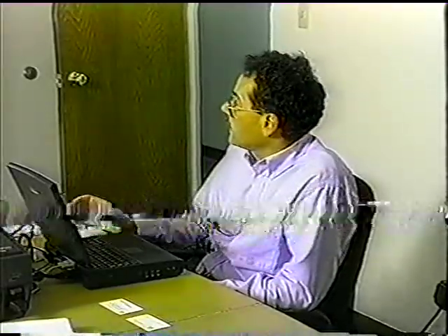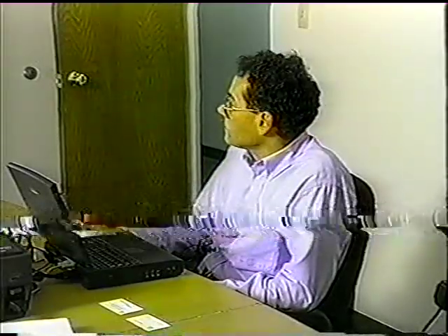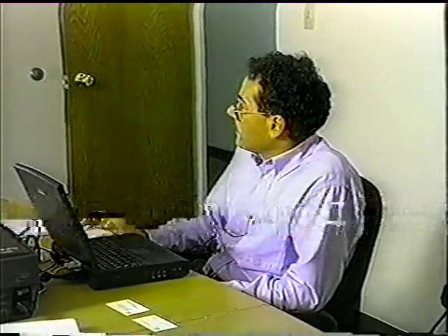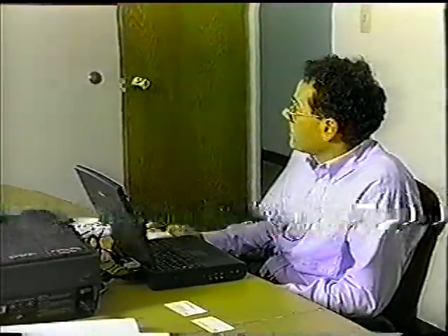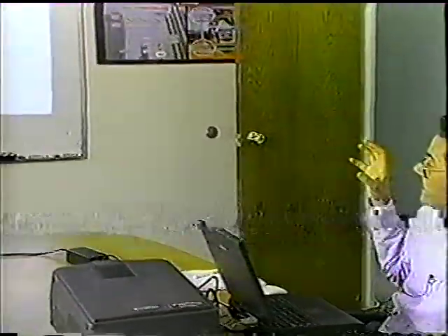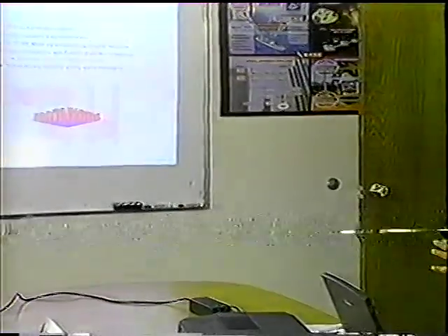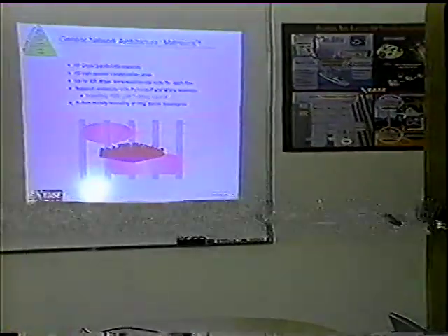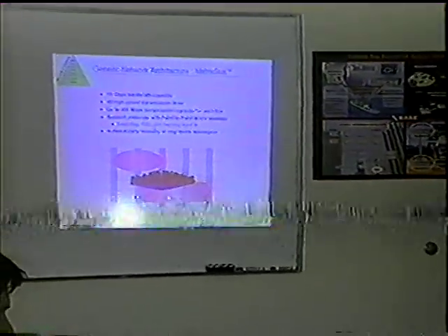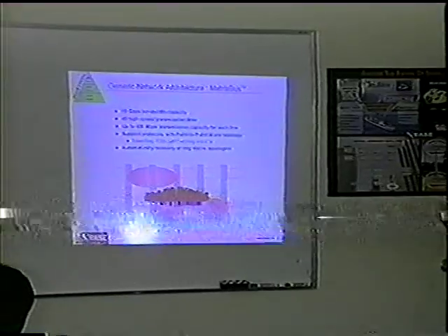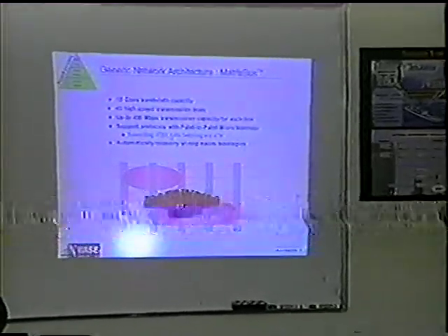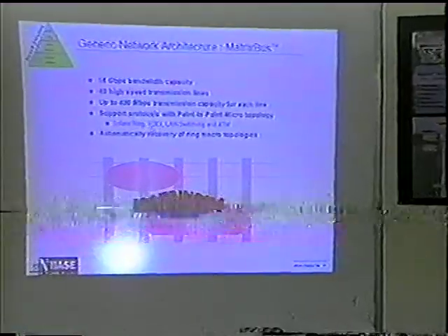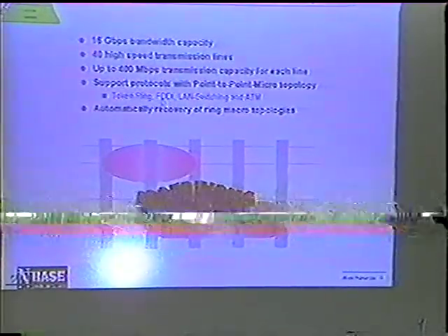And for the 100-base Ethernet, it's the same. We're actually running a 100-base Ethernet on the backplane. And the nice thing about the matrix bus is that you can run different protocols at the same time on the backplane. So you can have a 100-base Ethernet switching machine running on the backplane, and other cards can run token ring or FDDI or anything else. They do not interfere with one another.